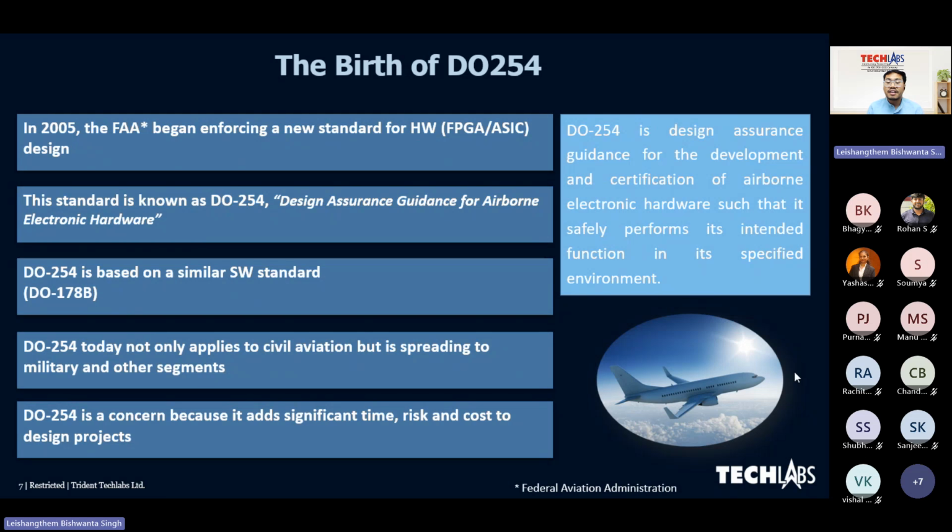The guidance was later reinforced, actually. It started as RTCA DO-254 in 2005, and the FAA in the USA and the European EASA started adopting it. Now we are in 2026, but around 2018 to 2022, this guidance needed to be more clarified, and because of that it was reinforced by EASA and FAA. EASA issued AMC 20-152A in 2020 and the FAA followed with AC 20-152A in 2022.